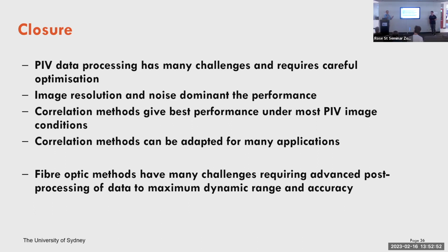But where it really gets difficult is when you have a volume and you're trying to track individual particles inside it, because you get lots of limits in terms of tomographic restrictions, and you get ghost images and you start tracking the wrong thing. It's probably exactly the same problems that you get in your field. There's been a lot of work done on tomographic PIV, but at the end of the day, a lot of it comes down to image resolution and the field of view. There's some physics, like Nyquist criteria, that you just can't beat.